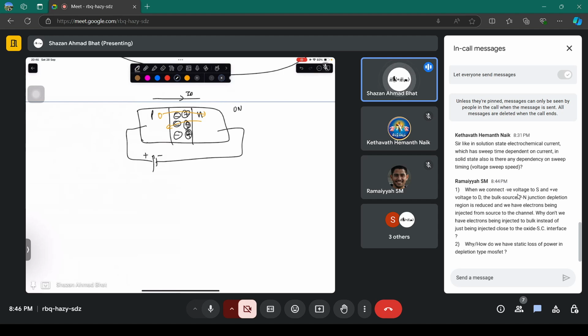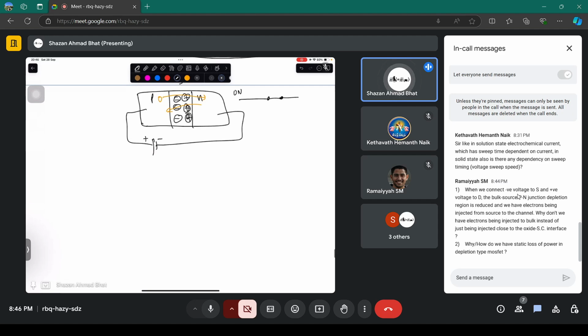So this is a normally on diode. That means this is the circuit diagram of this. What you do, just remove this source. You suddenly turn it off. There is certain time associated with charges moving back to the N and the P side. So the charges take some time to move back to the respective sides when you remove the applied potential.